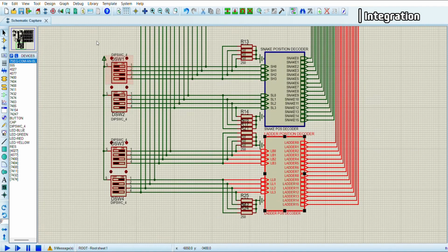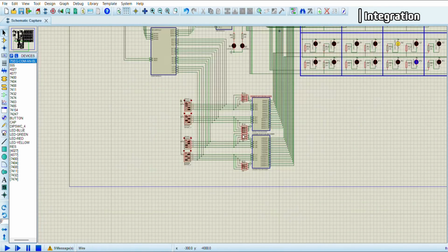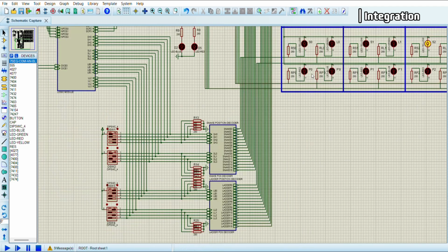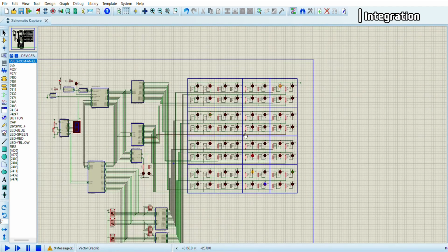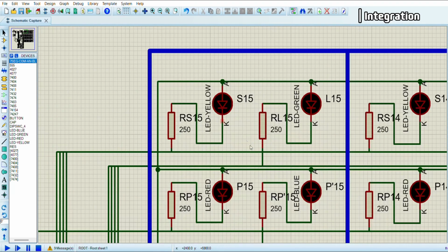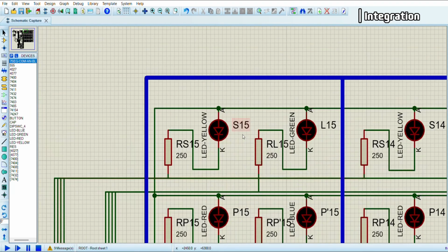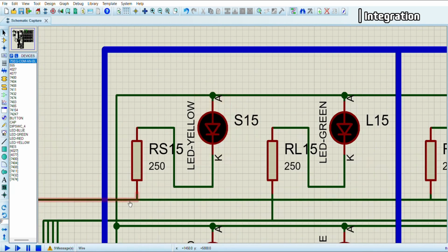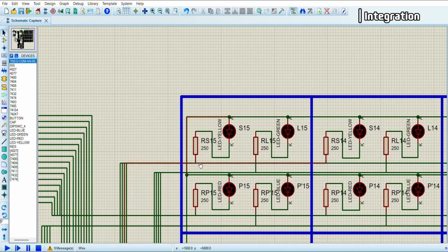This is our switch. So we also pass these things to the board module. In our board module, the LEDs are connected in the common anode configuration. So when we want to light up this LED, we just make this value 0, and then the LED gets lit up. And normally this end gets a 5 volt value, so the LED does not get lit up.